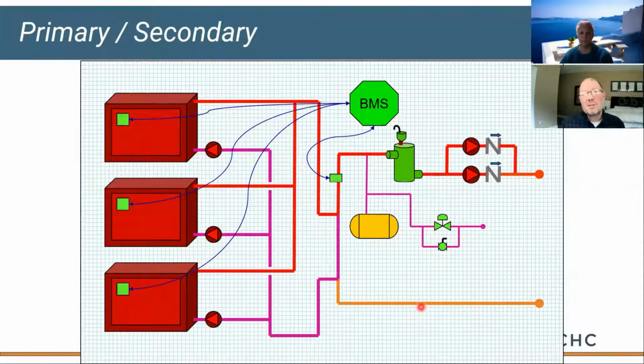Here's another example of primary secondary with multiple boilers in this case. And again, these could be boilers or chillers, but for this talk this afternoon, I'm just sticking with boilers. Now you'll notice, again, we kind of have some not so closely spaced T's, but that's all relevant based on scale and line size. You'll notice that each boiler in this case clearly has its own dedicated pump, and each pump is going to be sized for the amount of piping from the system back to the system.